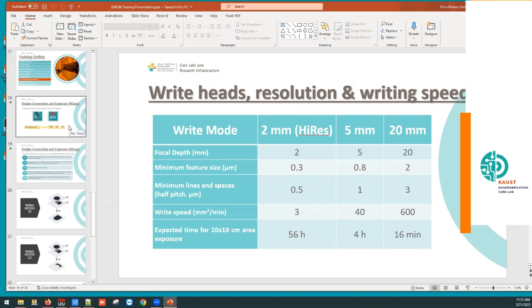I ask this because in the mask software, we need to set the 0, either in the middle of the design or in the left bottom of the design. So does that mean we also need to set the 0 coordinate in the middle of the design before we prepare the file? Yes, I mean, because one thing is it's not setting the 0, okay? Because what the tool is doing when you load the sample is just scanning the full area to detect what is the edge and then calculating exactly what is the center, not the 0, because there is no design for now. When you just load the plate, the tool knows where is the center of the plate.